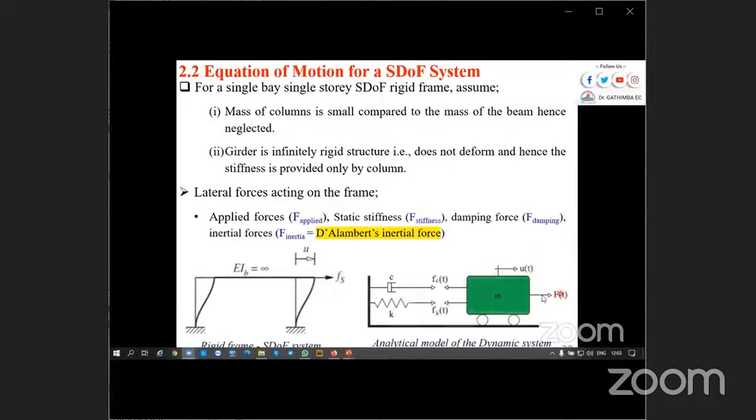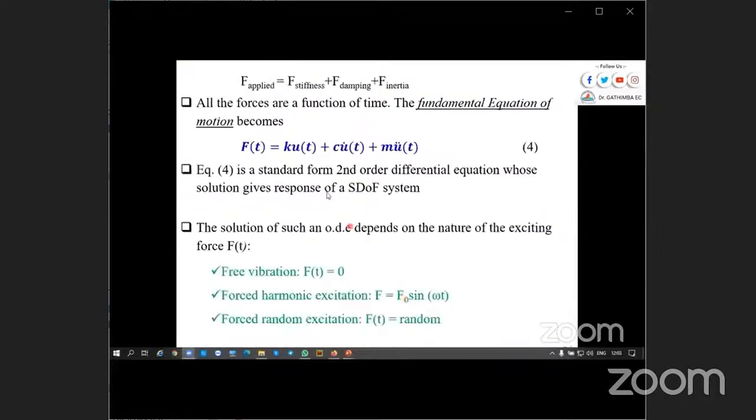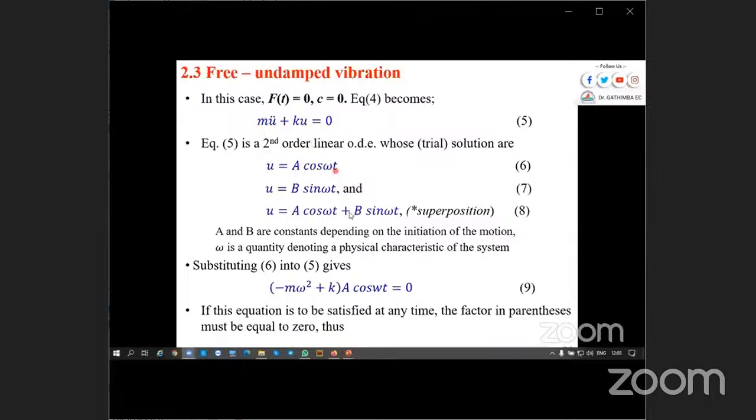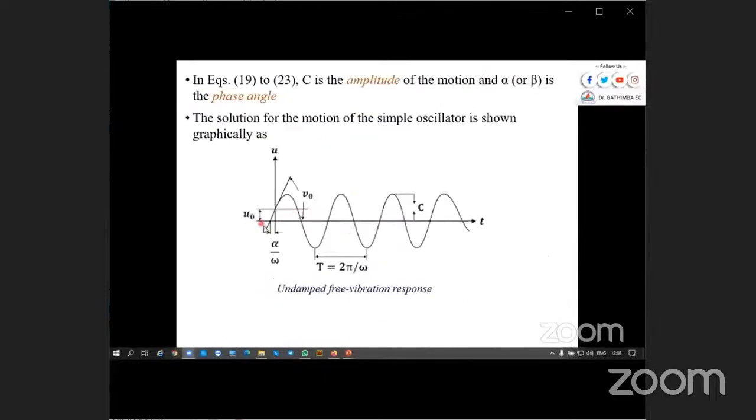It's even like a pendulum, 2 and 4, 2 and 4. So this motion of our structure, we have expressed it in this form, equation 5, and the solution of that equation is this motion. We are saying because of the applied external force and the damping that is known and the stiffness of the column that is known already, at any one point we can describe the motion or the position of our structure using this solution. This is the solution, because it will be varying at different times. We have the amplitude. So as time t is equal to maybe 3 seconds, we can say this will be the displacement.